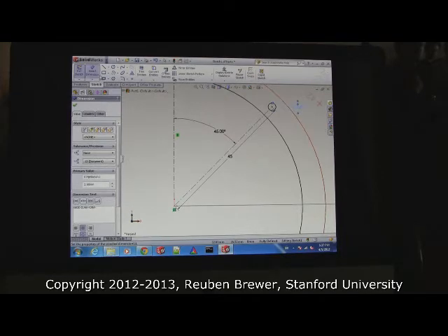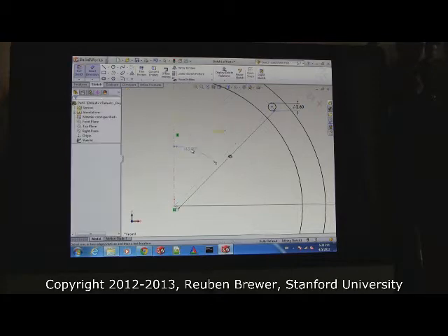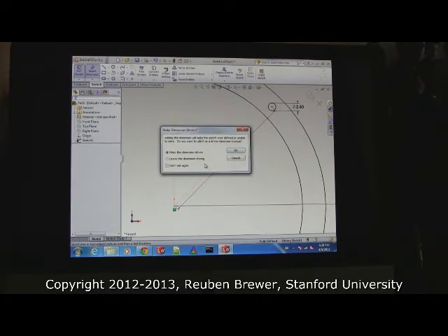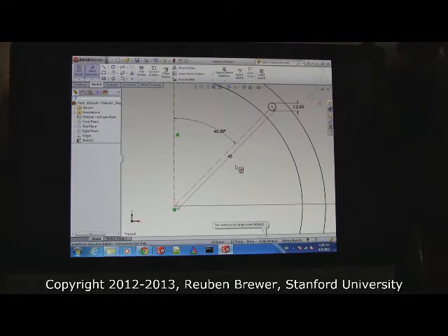Yeah, so here, I'll show you. So now I'm going to try, maybe I changed my mind and I want to make this 60 degrees. See? That's the error. That means I've already set the dimension somehow and it won't let me do it again because then it would be over-constrained. If that happens, it means something went wrong. And now see it says the sketch is no longer over-defined. When that happens, you have to search in your sketch to see what is incorrect. Click on this line.